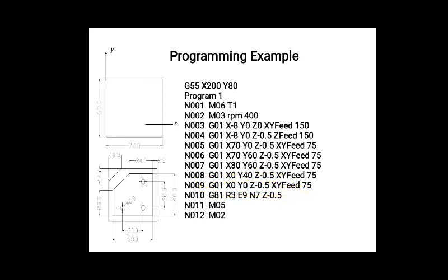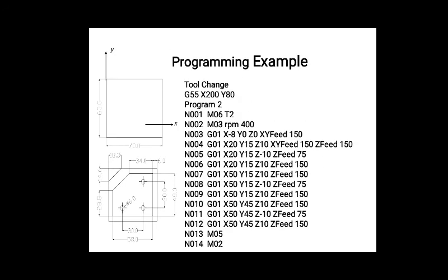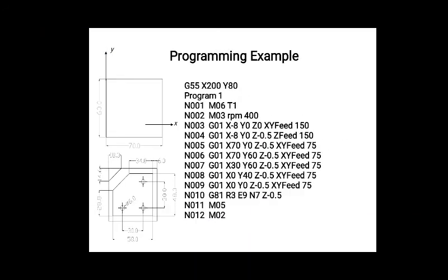And after that, we are going to repeat this cycle from block number 3 to block number 9 with an incremental depth of cut of 0.5 mm.